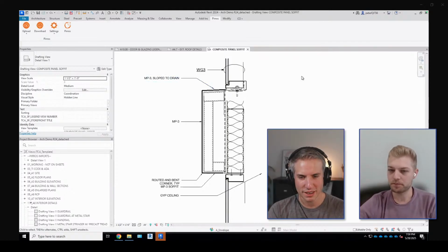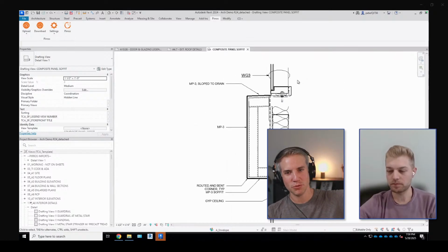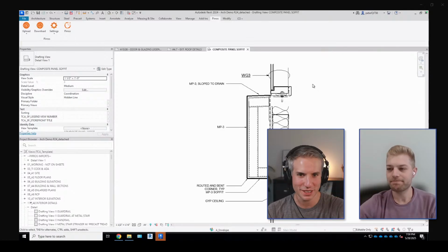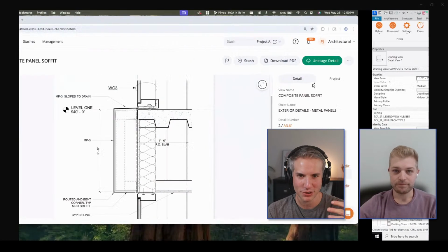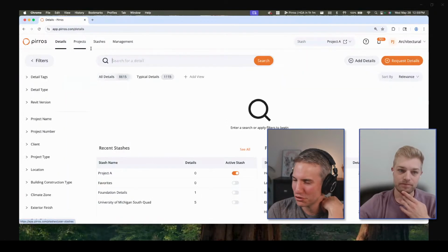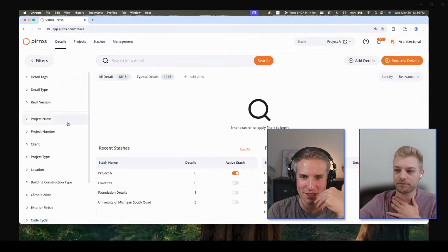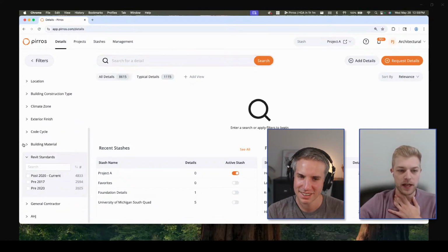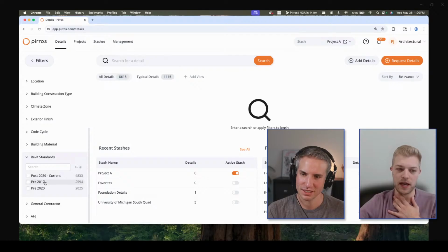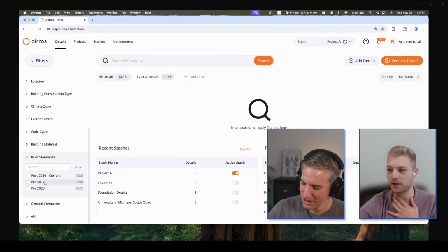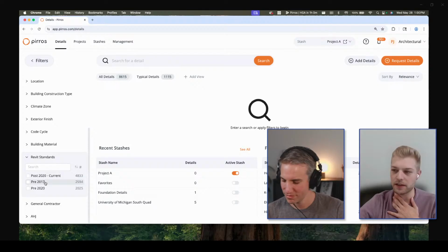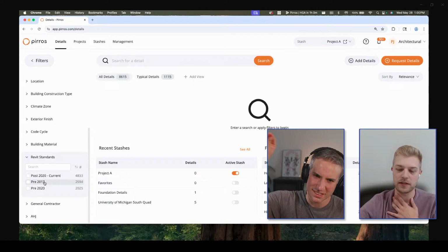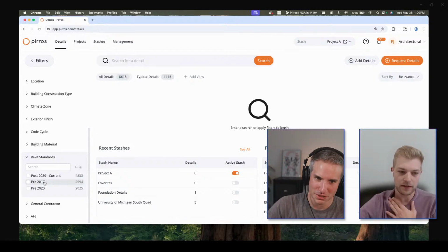So how would you deal with, let's say that you have the problem with a kind of 10 years old detail? Sometimes it's an old line style, old detail item, they're outdated, old patterns. So how would you try to fix it? Do you upload to a new project? You swap with new elements and upload it back to the platform? Yeah, you can utilize these Revit parameters. So you can label, hey, all these projects that we designed pre-2017, they're going to be in old Revit standards. They're going to be add line types. They're not going to be in components. So that's a tag, like old standards, new standards, and so on.